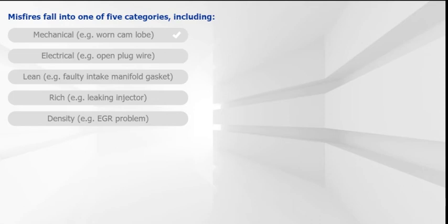If the cylinder is leaking because of a blown head gasket, for instance, the mixture will not be adequately squeezed during the compression stroke. Under this condition, the piston will be unable to compress the mixture sufficiently to produce the required increase in cylinder pressure prior to ignition. Finally, unless combustion byproducts are quickly discharged from the cylinder during the exhaust stroke, the incoming air-fuel mixture will become displaced by lingering gases incapable of supporting normal combustion. Consequently, an inactive exhaust valve is another potential cause of a mechanical misfire.